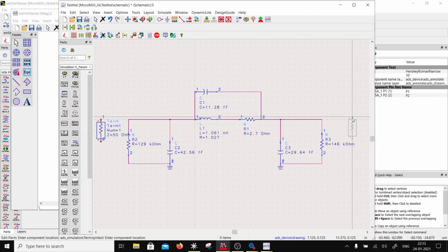Now who might like to do this model? People may just use an S parameter file. But if you want to improve your inductor in a process, you should know where your resonances are coming from. So probably I can advise these foundry guys that this 42 and 29 is way high.